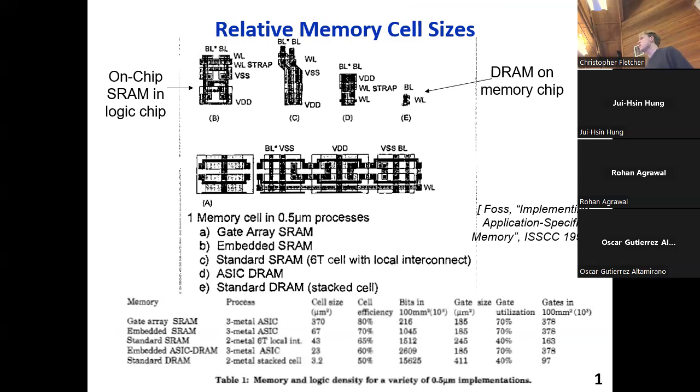Furthermore, and this is not a law of nature necessarily, but it tends to be the case, going back to what we said made SRAM fast relative to DRAM, the access latency of your cell is also proportional to the size of your cell. So the size of the aggregate memory impacts latency. The size of an individual cell also impacts latency, and it is inversely proportional.